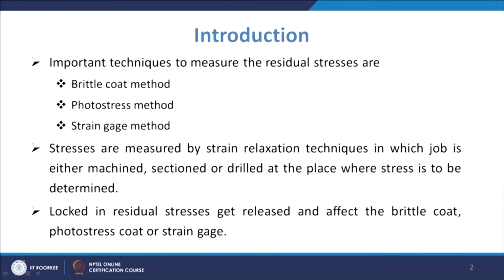So, we will talk mostly about the destructive type of methods which are used for measuring the residual stresses in the weldments. The common techniques available to measure the residual stresses are the brittle coat method, photo stress method, strain gauge method, and also other methods.